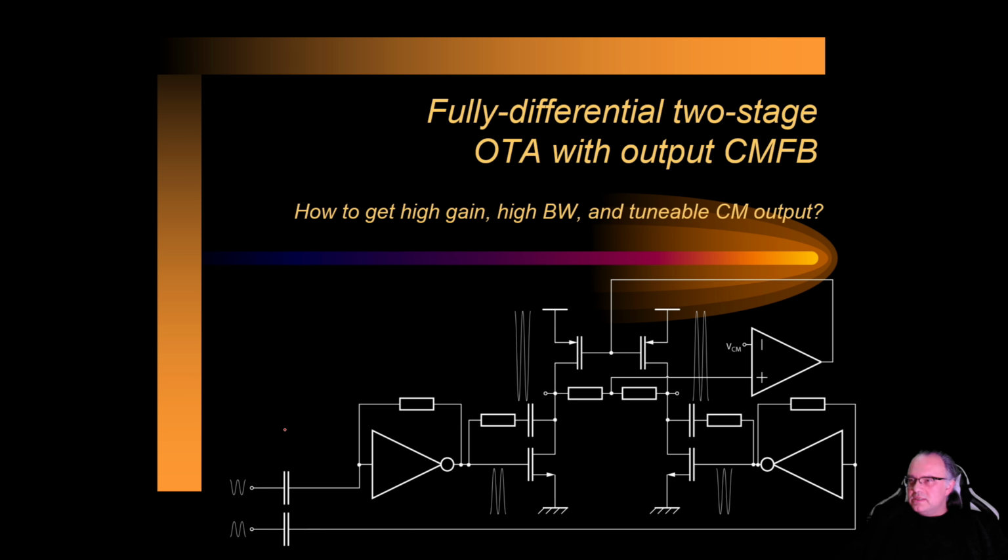Just to recap, if this is the input and this is the output of the amplifier, the transfer characteristic of the inverter is like this, and this is the optimal operation point where the gain, or the slope of the transfer of the signal, is the highest. So we amplify the AC component of the signal somewhat here, about 30 dB for example, as demonstrated in my previous videos, about the optimum of this technology.